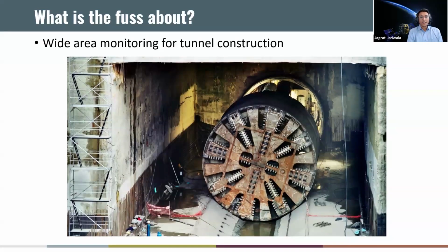The other civil engineering application is tunnel construction. Now imagine you have historical information and you can come up with baseline movement estimates of buildings and structures in the zone of influence of your proposed tunnel construction. And now you already know which buildings are moving faster, and you can now modulate the on-site and more conventional monitoring so that those things are captured.